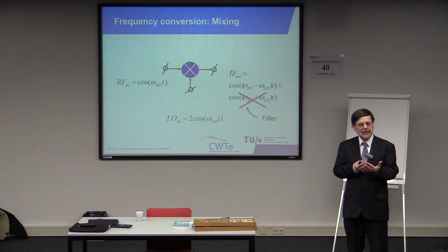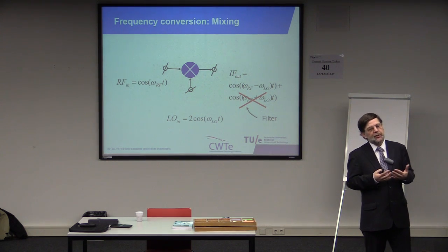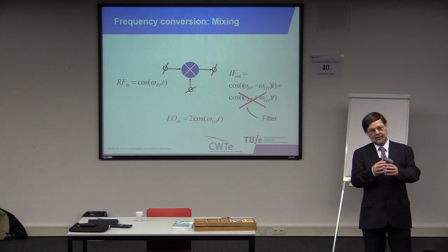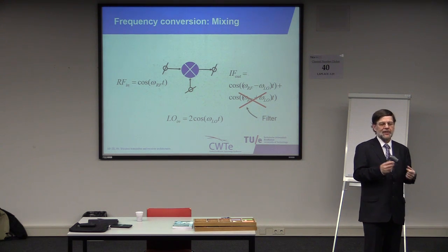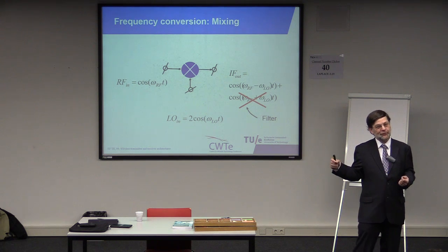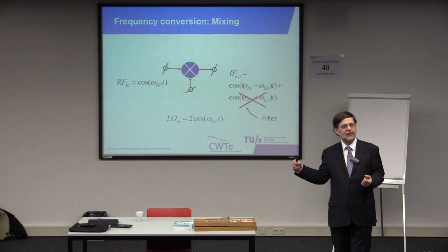Nevertheless, we need something nonlinear, and so many things are nonlinear. And anything that's nonlinear, you can model, you can describe using a Taylor series. Right? You can describe as a polynomial that says the output voltage is the input voltage times some coefficient plus the input voltage squared times some other coefficient plus the input voltage to the power of 3 times yet another coefficient, and so on.